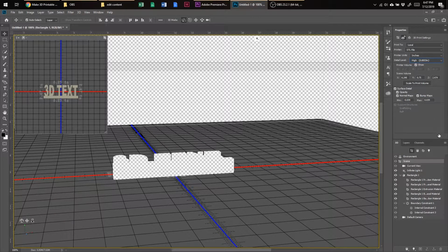To export this, all we have to do is go to this item right here, which is literally a 3D printer because it has a little print icon right there for 3D printing. It's going to generate a mesh. It's going to repair whatever meshes we have, because sometimes your text can still be generated bad in a 3D image when you go to convert it, and this is just going to go in and try and fix any of that ahead of time. And if there is a problem, it will show you in the options, but we'll come back in a second when this is all done.